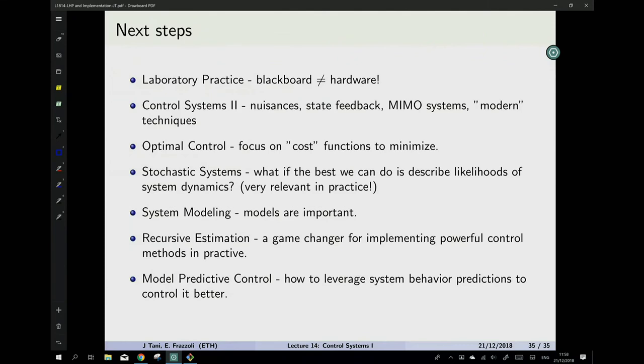So you take your model, you predict the future, you make a strategy, you design a control input based on the prediction of the future, and as time passes, you adjust your prediction every time, okay? It's a fascinating and very practically useful control method for very complicated problems. When you have really lots of things and you have 32 inputs, 44 outputs, optimality, constraints, stuff, model predictive control, okay?